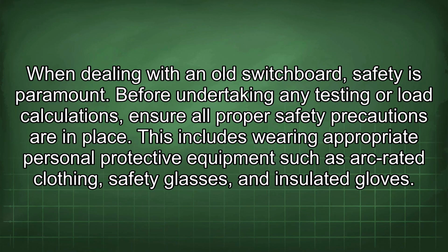When dealing with an old switchboard, safety is paramount. Before undertaking any testing or load calculations, ensure all proper safety precautions are in place. This includes wearing appropriate personal protective equipment such as arc-rated clothing, safety glasses, and insulated gloves.